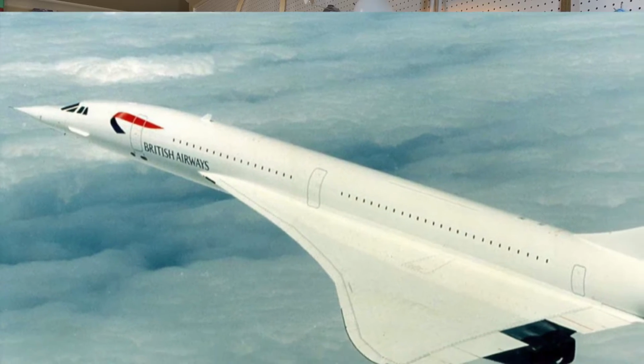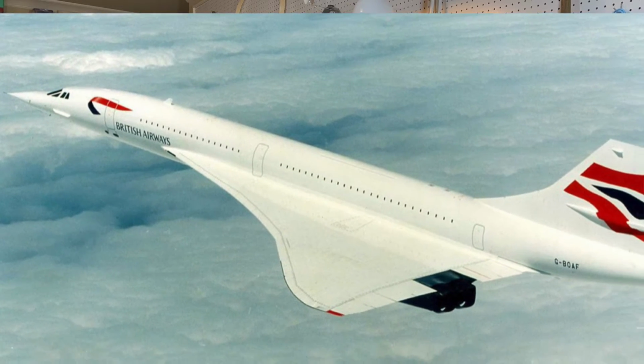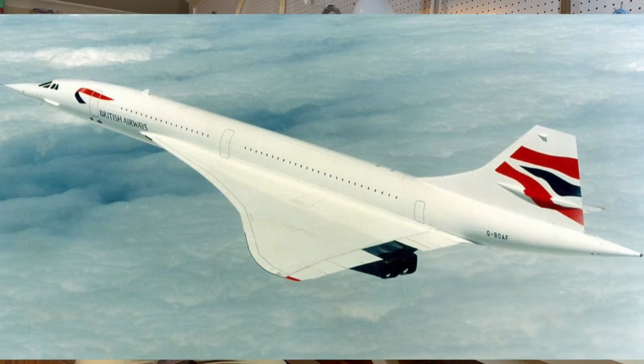And there are some very advanced aircraft that will actually move fuel between tanks during flight to achieve the proper center of gravity. A very good case of this is the Concorde, the supersonic transport. Because of the unique aerodynamic features of supersonic flight and trim associated with those extremes of flight, and the Concorde went twice the speed of sound, which is very fast, there's not too many airplanes that can do that.